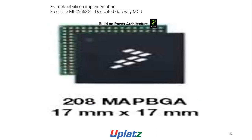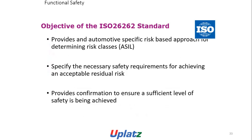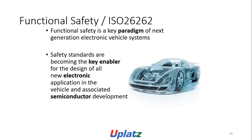Example of Freescale MPC5668G, a dedicated gateway MCU built on Power Architecture, 208 MAPBGA, 17 mm by 17 mm. Objective of functional safety: the ISO 26262 standard provides an automotive-specific risk-based approach for determining risk classes, ASIL, specifies the necessary safety requirements for achieving an acceptable risk, and provides confirmation to ensure a sufficient level of safety is being achieved. Functional safety, ISO 26262.